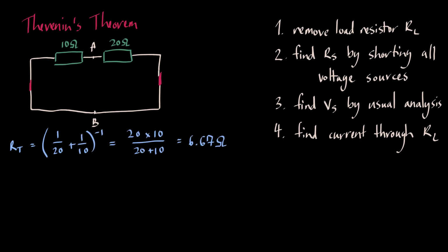We now find the equivalent voltage Vs. This is the voltage across the terminals and also can be considered VAB. We do this by reconnecting the two voltages back into the circuit and finding the current about the loop.